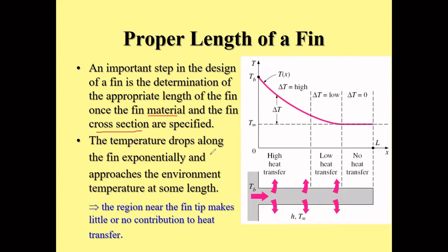The temperature drops along the fin exponentially, right? So the temperature drops exponentially and approaches the environment temperature at some length. The region near the fin tips makes little or no contribution to heat transfer. At one point you will see that there is no more heat that can be transferred to the surroundings because the temperature has already reached the ambient temperature.